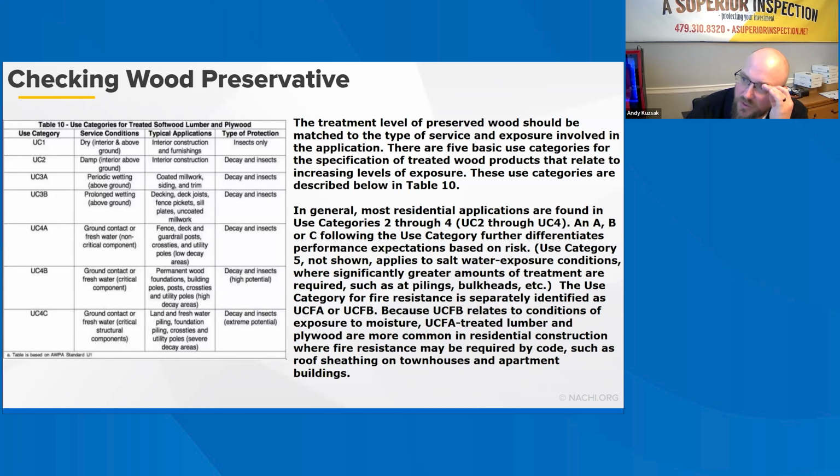In some cases, wood alternatives can be used, such as plastic porch posts with metal pipe inserts, plastic decking, concrete posts or piers, or plastic lumber composites. The focus of this section is on identifying proper specifications and use of preservative-treated wood to ensure moisture decay resistance and durable performance. The recommendations in this section are based on the standards and recommendations of the Southern Pine Council and the American Wood Preservers Association.